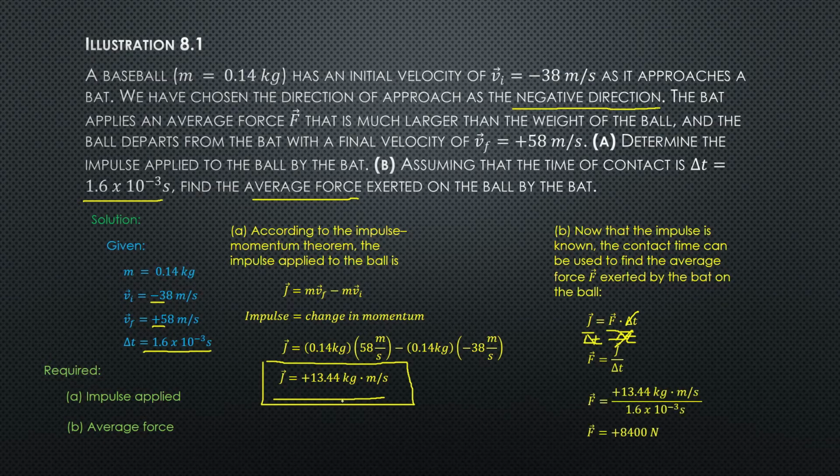Substituting the values, we get 13.44 kilogram meter per second divided by 1.6 milliseconds, and that gives you a positive 8,400 Newton force.